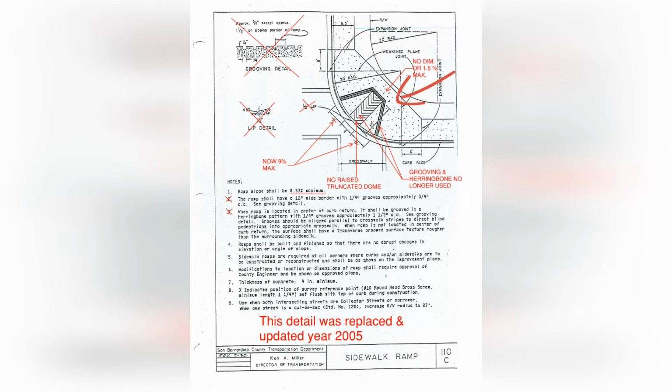The landing at the top of the ramp did not show a grade of 1.5% max in either direction, or a distance showing the length or width of the landing. The only grade that can currently be used on this detail is the ramp run slope itself at 8.33%. But even this slope is the maximum as-built slope and was often constructed over these limits.